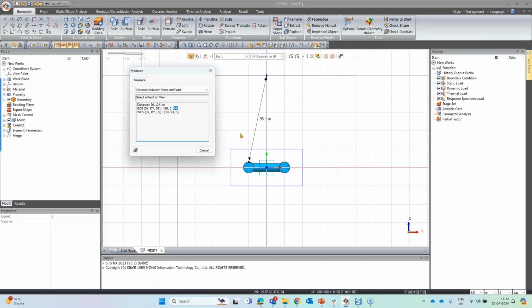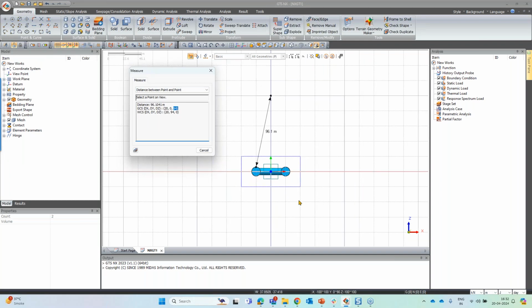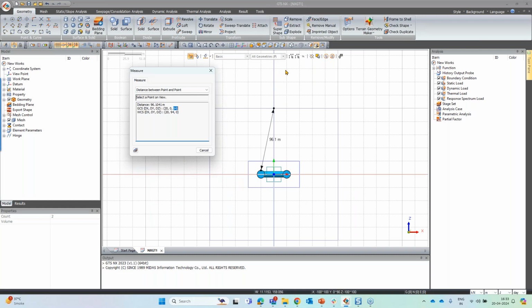So we have around 906 meters still not modeled. Instead of modeling the entire 1 kilometer overburden directly, we will apply the additional 900 meter overburden as a pressure at the top. Okay. So we'll just ignore the 6 meter overburden, and we will model the 900 meter overburden on the top.